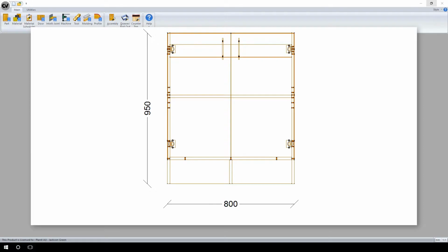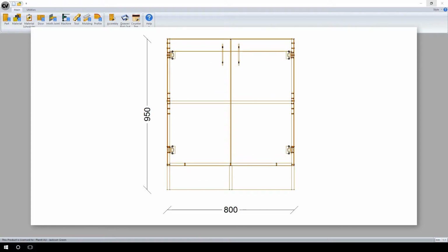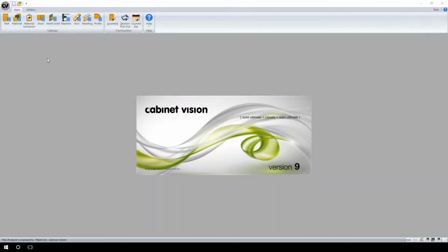Here we can see a cabinet that has had the rail rotated without equations applied. The rail will not stretch with the height of the cabinet. The following shows the exact same cabinet with equations applied. The rail will now properly adjust with the cabinet. This is to highlight a basic example of what we will achieve with Object Tree.